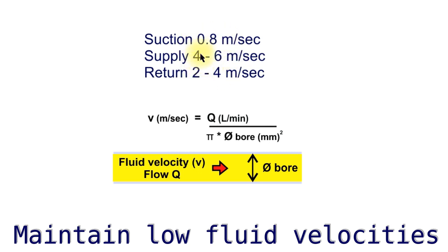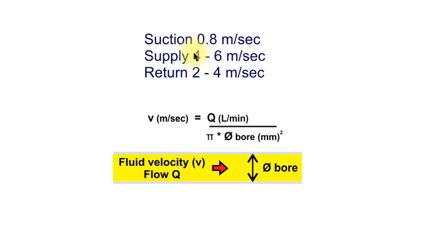Now, if you're making one-off systems, you want it to work, no issues, stay with the lower values. If you're doing lots of machines where you want to keep your pipework costs down, but you can actually test the system to make sure there's no issues, you can push to higher values. There are lots of reasons why we'd want lower or higher on different machines, but the manufacturers will set these and test these. But yes, stick to the pipework sizes, don't go over different sizes in the different areas and designs, and if you can, check it to make sure you're within reasonable limits.